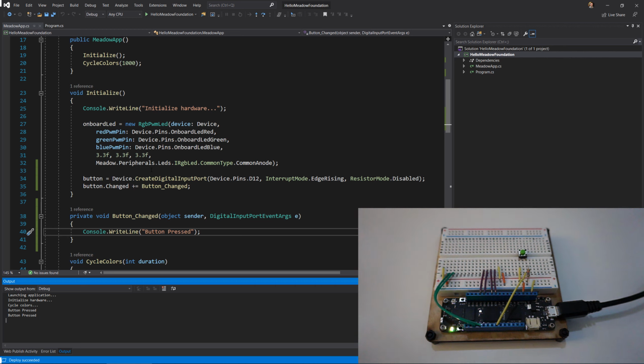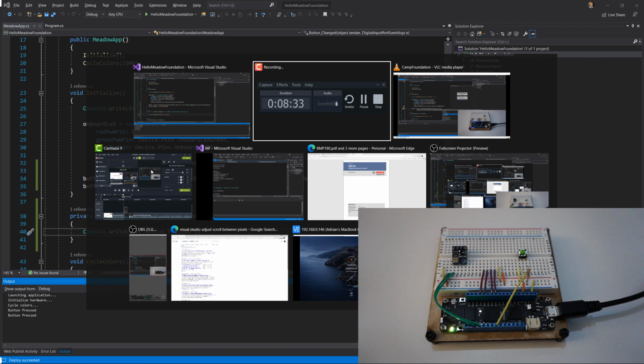Just so happens that I have one here. This is the type of BMP 180. I'll show that there, and I'm just going to throw it down. I'm going to leave it up here for the moment. Have a look at it. So hopefully you can see it has 4 pins on it, but how the heck do we know how to hook it up? Well, turns out most of these things are very well documented, and for the BMP 180, we could go look at a spec sheet.